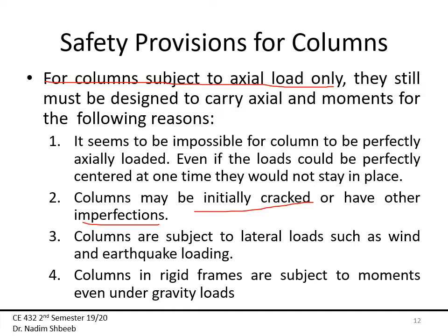Again, if I have wind loading, forget it, you're going to have a moment. If your column is part of a rigid frame, then you're also going to have a moment. So we always do, even if there are some instances where the moment isn't that big, we always account for about 10% of that for tension reinforcement, and I will get to that when we go to the interaction diagrams.